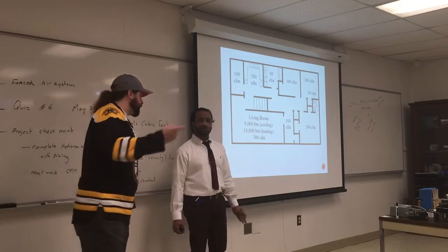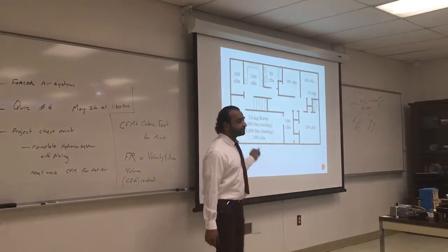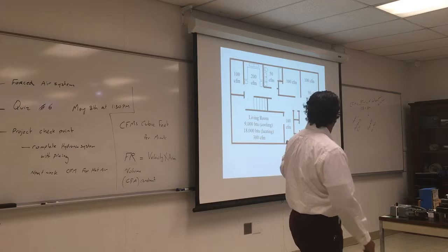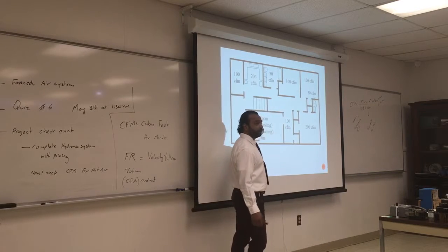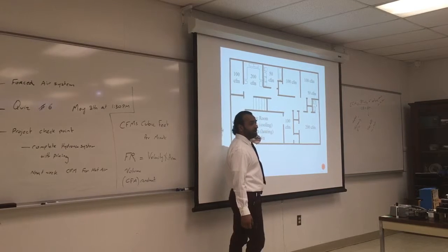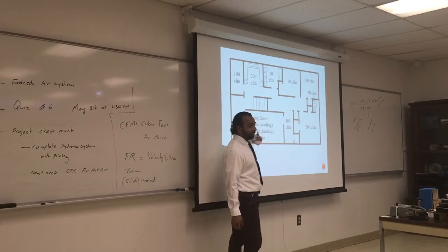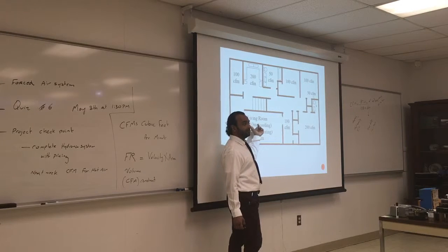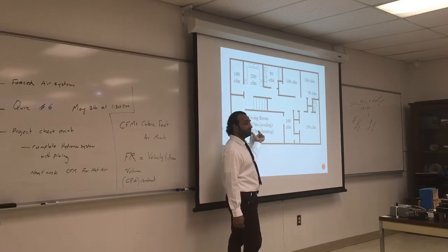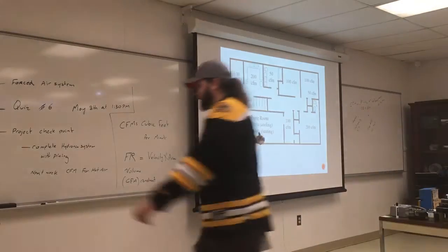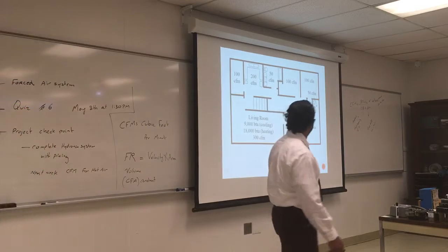So we will size for the heating, because it's higher, and you can always step down instead of going up. What happens if I size for the cooling? You're not going to get the proper heating? You can, but you're going to have to pump up the velocity, right? It's going to be very high velocity, and that will lead to what? Noise, discomfort, and high draft. So you don't want to have that.